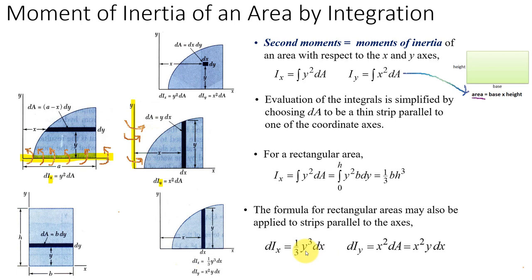If you have an equation for y, so y equals some function of x that you can plug in here, sometimes it's easier to use this 1/3 trick when integrating, versus sometimes it's easier to use this dA trick. So compare this first equation, y squared dA, with this other equation, y cubed dx. They end up giving you the same thing, but depending on what equation you have, one might be easier to integrate than the other. And we'll have some examples using each of those methods.